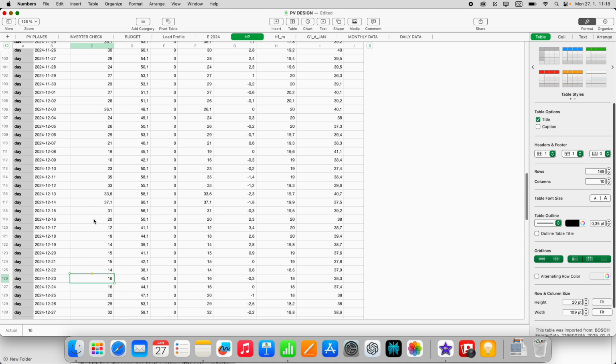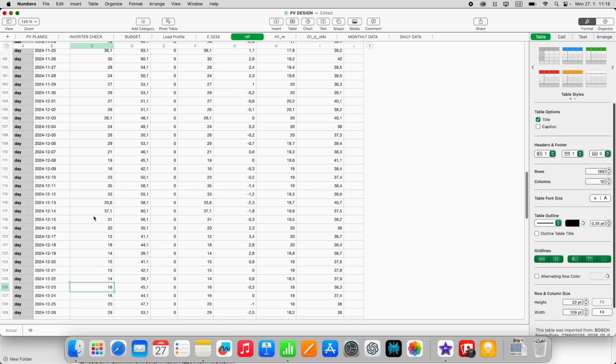Or we're going to have a look at snow data a little later. So in this location, there's actually quite high potential for snow coverage in winter. And so you want to be safe by assuring that the panels are not going to be covered in snow. We're going to see what the data says. However, it's also not very precise to base it just on that data, because the amount of newly fallen snow doesn't always mean it sticks to a slanted roof or a gable roof.